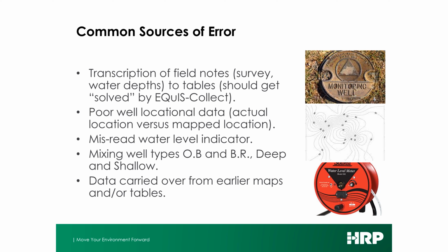But if you can avoid it, I would rather draw an overburden map separately that doesn't go into the area where the bedrock is higher than the water table. And if I have the data, draw a separate map for the bedrock wells, if there's enough to make it worthwhile.